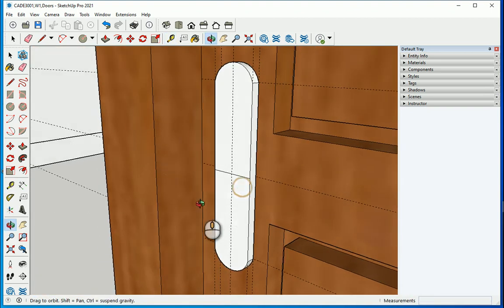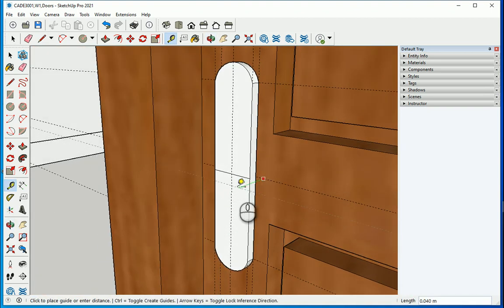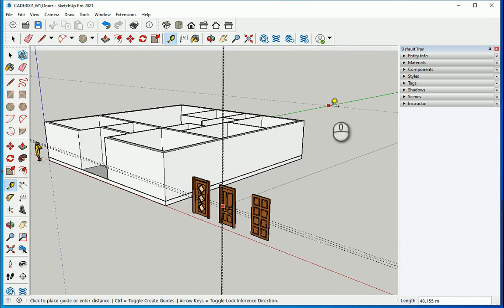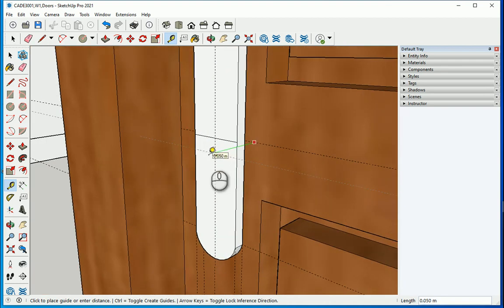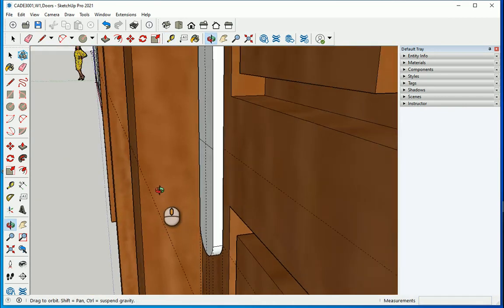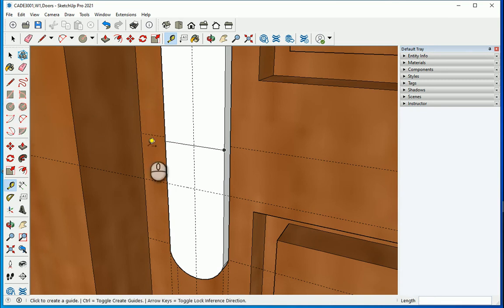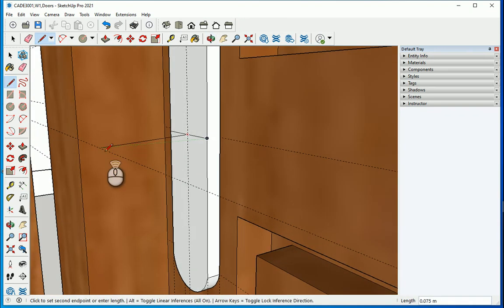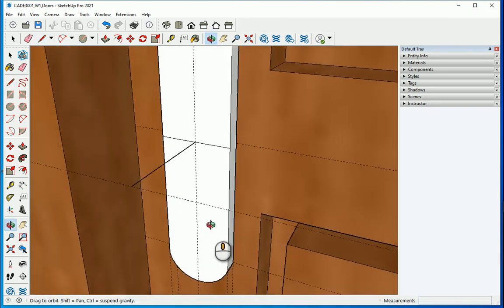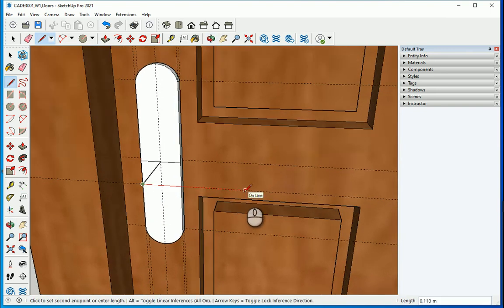and I want to draw another reference line, but notice that it's in the green axis. What is the green axis here? It's the y-axis as we talked about before. So I'm going to consider, let's say, about 8 centimeters, 0.08 around here, right? So how about I draw one line or L? Shortcut is L, the actual icon is this one, and I'm going to draw from here to this line, right? And maybe I can draw like 0.2 from here.